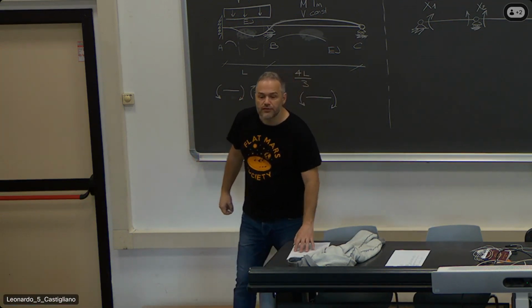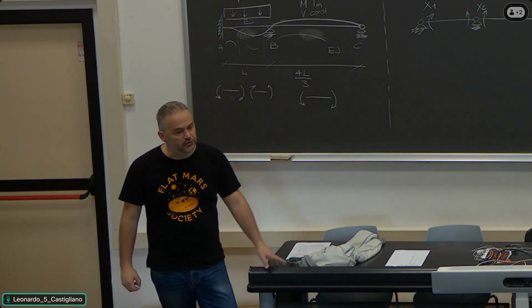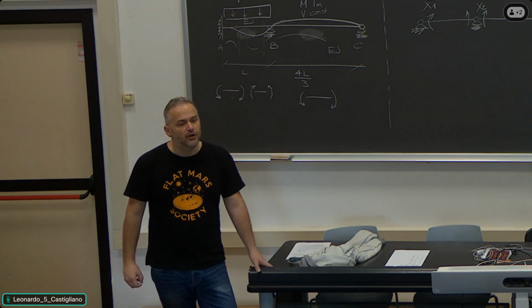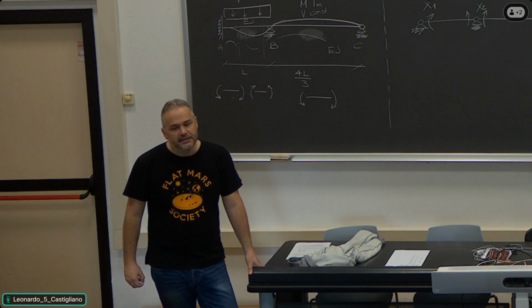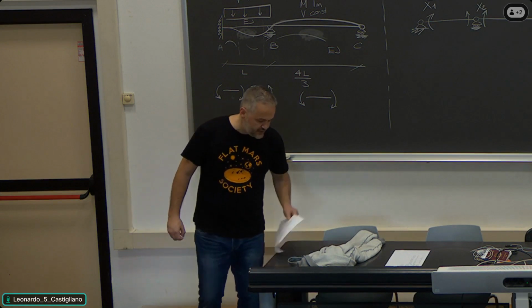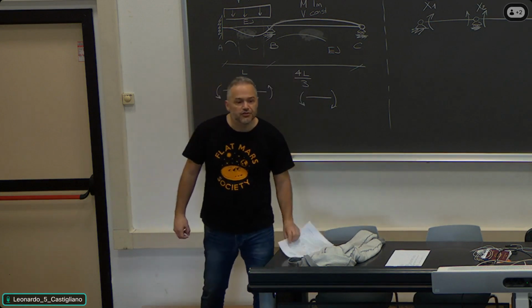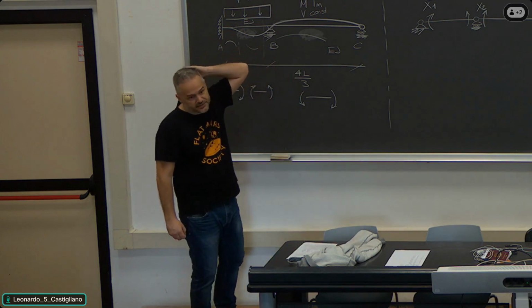So how do we solve it? You know, the conventional way to solve such a structure with these two unknowns is to separate all the causes and the corresponding effects. And specifically assuming all the unknowns to act with a unit value in order to be consistent with the standard coefficients we have. All the forces except, of course, the externally applied loads.